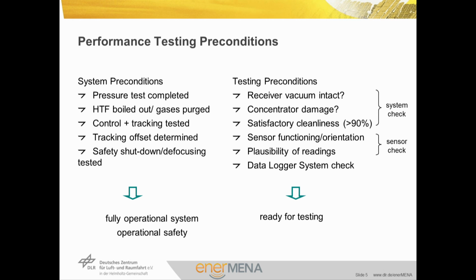As for the start of a new testing campaign, at the beginning of each test, the observation of the following preconditions is essential. The system should be checked thoroughly in terms of full function of components. Are the receiver vacuums intact? Is there damage to the concentrator? Is the cleanliness satisfactory? Furthermore, sensors should be checked in terms of functioning, possible orientation, and the plausibility of the readings. So should the data logger system be checked. If these testing preconditions are met, the system is ready for testing.